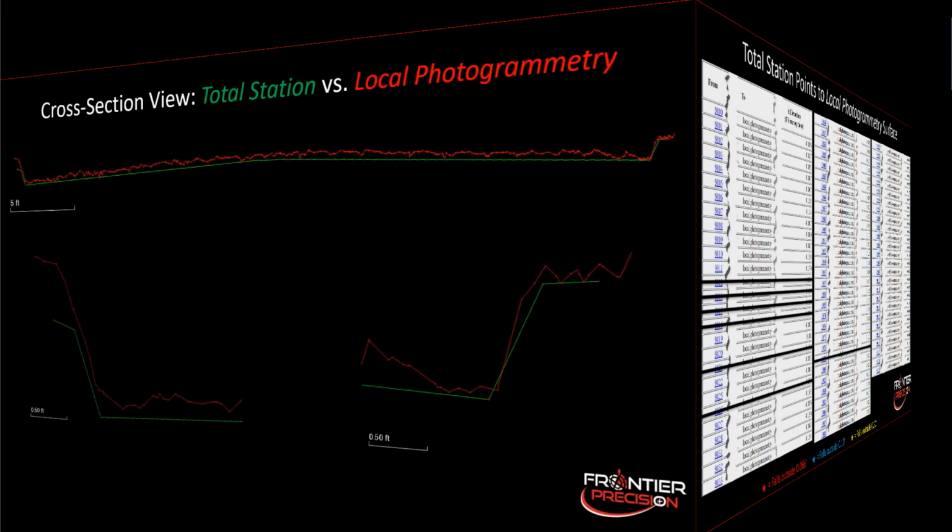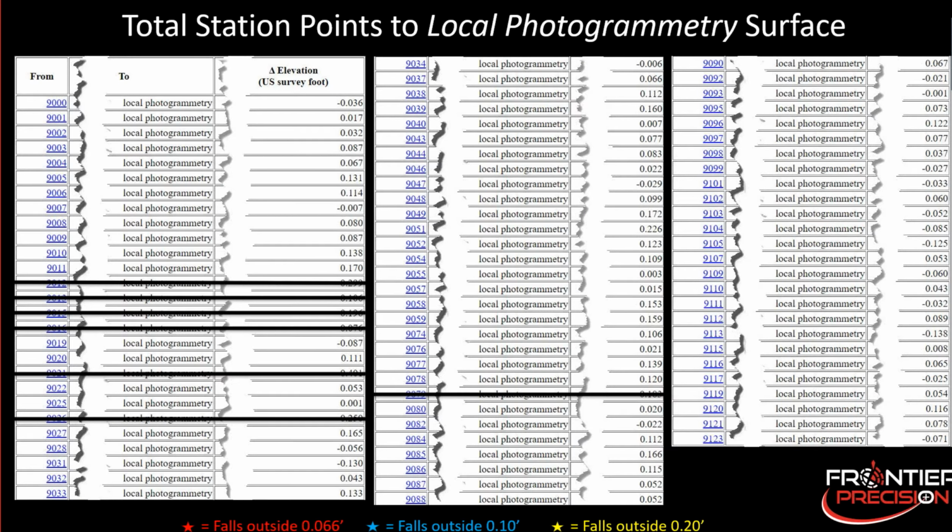And then lastly, getting to this, this is me comparing the photogrammetry surface again to those total station cross sections we took. And some of these points I have crossed out here, and I just want to explain that. We collected this data at various times and various days, and it's the fall here in Minnesota. So we went through because we had some outliers, and there's different spots where there was a pile of leaves in the gutter line or something like that. So any of those points where there's some question where there's missing data or there's stuff in the gutter of the road or debris that we have to deal with, we just threw those points out. So that's why they're crossed out.